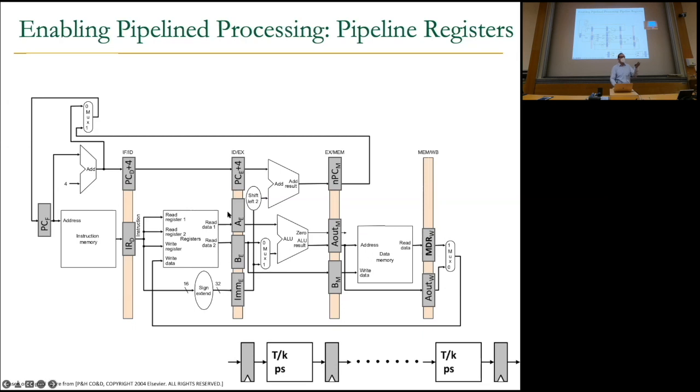As we will see, it'll grow even more with control signals. This is just a data path right now. In the next cycle, you'll start processing this instruction in the execute stage or address calculation stage. As you can see, there are resources for both. Then the next instruction gets decoded over here, and the next instruction is being fetched. The ALU produces a result, and you put it over here. There's some B register over here that's potentially used for stores, as you remember, and then there's an XPC that you may use.